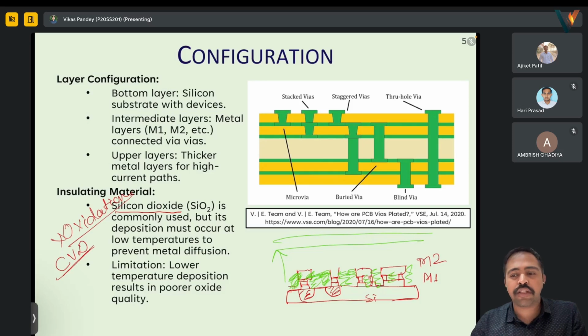When we are doing sputtering, yes, you are right that some temperature rise will occur even if we are not giving any temperature, if it is done for a longer time. But a metal can sustain 70-80 degrees, that's not an issue. Okay, thank you. And ALD will actually be much costlier as well as time taking if you compare ALD and sputtering.